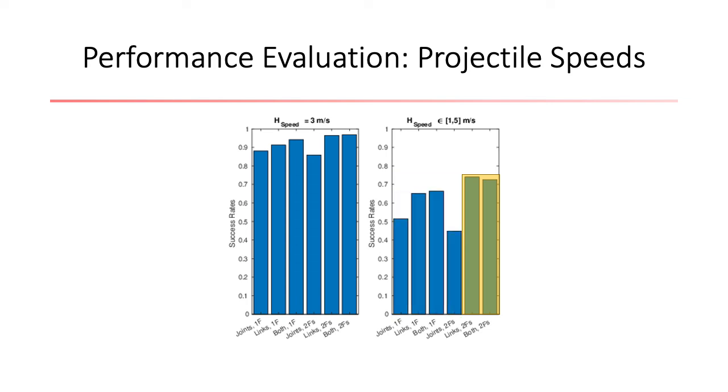The most resilient are the 2 frame links and combined types, followed by the one-frame links and combined types, while joints one-frame, and especially joints two frames, generalize poorly. The most plausible explanation is that policies with link observations learn to minimize projectile stick distance, while policies with only joints learn mappings from joint angles, projectile position combinations to robot actions, which would be expected to be more brittle.